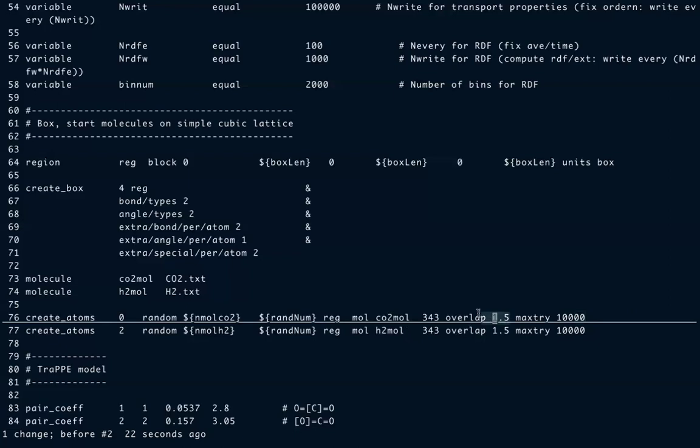And yeah, if it does not succeed within these many tries, then it shows a warning message that it could not initialize all of the molecules. So please be very careful here, because it can happen that if you intended to specify 100 molecules of CO2, of course not in this case, but if you wanted to specify 100 molecules of CO2 in a very dense phase, it could only end up putting together, say, roughly 30 or 40 based on the conditions you've chosen. So kindly check this in the simulation script.